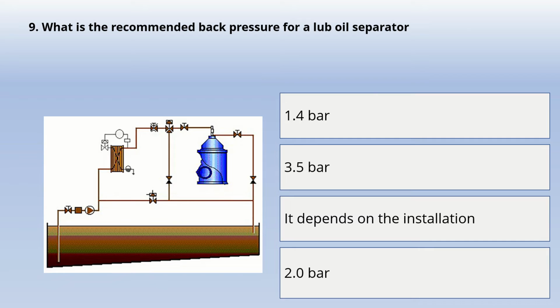Our next question is, what is the recommended back pressure for a lube oil separator? And the options are: 1.4 bar, 3.5 bar, it depends on the installation, 2.0 bar. And the correct option for this question is it depends on the installation.